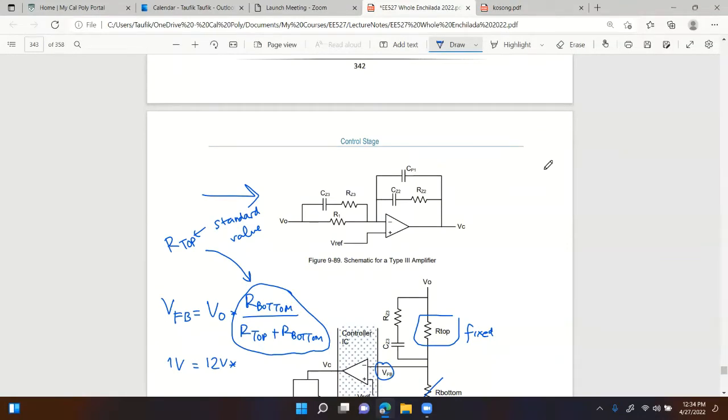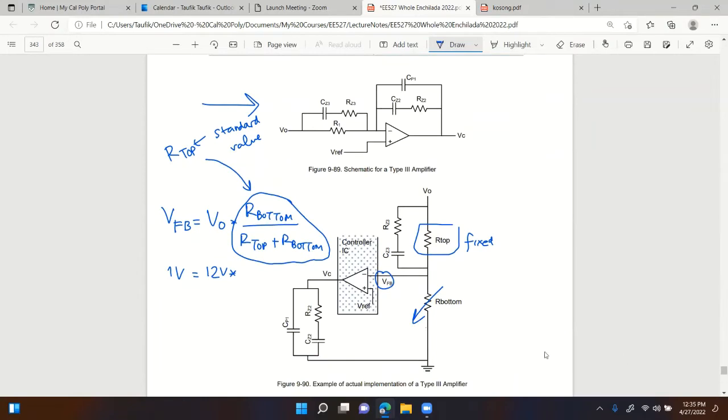So that's probably why, if you're not sure, it's wise to provide a trace on your PCB, just in case you need it. So this trace right here. At the beginning, you don't use this trace, and there's a pad for the resistor and capacitor.